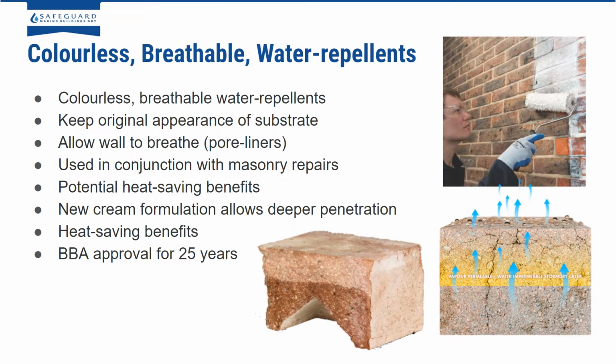And the idea is that they penetrate into the brickwork, approximately about 12 millimeters into the brickwork, and line the pores of the substrate. And the idea is that instead of blocking the pores, they line them, which allows the wall to breathe. So it's been found through testing that these creams only reduce the breathability of the walls by a maximum of about 10%.